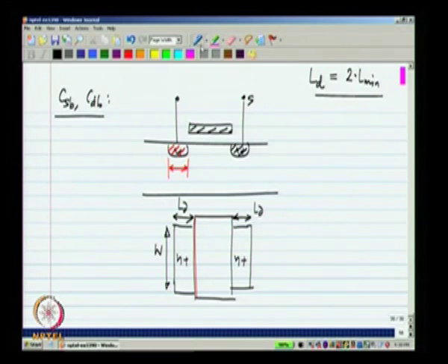And as usual, we do not have control over this depth. That is why we do not want any parameters describing the depth. If we know the depth times W, that is the sidewall area, but we do not want any of that, the depth is fixed. So, the capacitance is described as being made up of 2 pieces, one which is the overlap area at the bottom, which depends on W times LD.